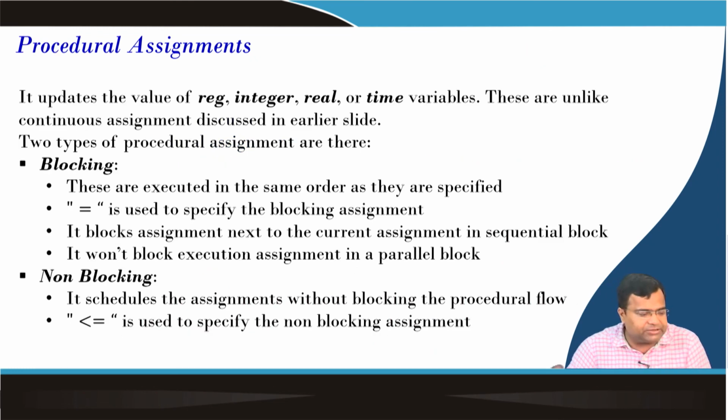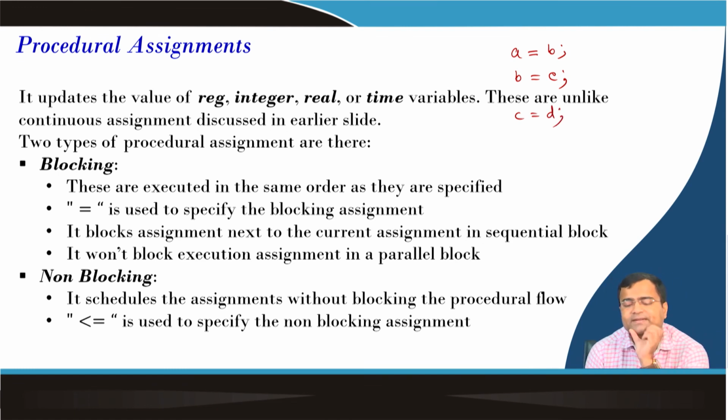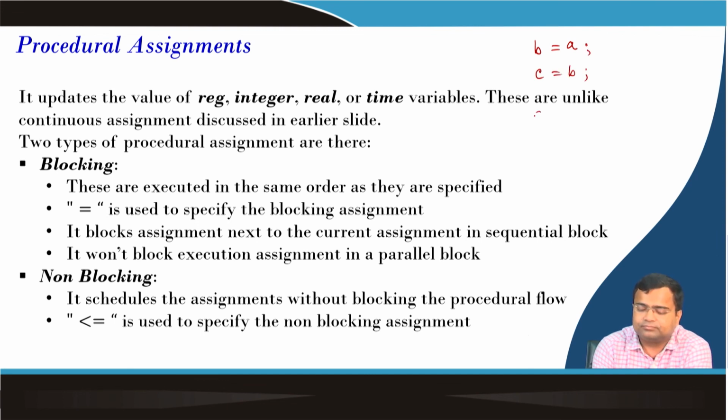Then procedural, that means you want to execute blocking and non-blocking statements. Suppose I am writing B = A, then C = B and D = C. This is called a blocking statement.